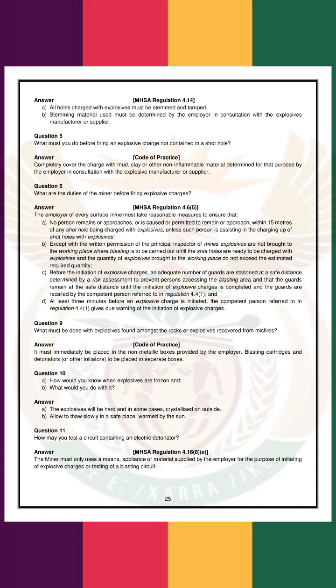B. Except with the written permission of the Principal Inspector of Mines, explosives are not brought to the working place where blasting is to be carried out until the shot holes are ready to be charged with explosives, and the quantity of explosives brought to the working place does not exceed the estimated required quantity.